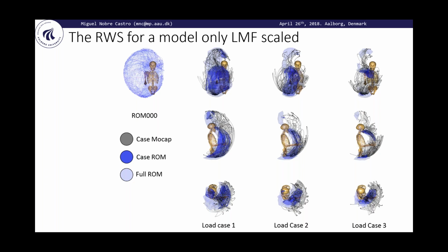So in order to assess that, what we also did, and as you can see here, these light blue clouds that I'm also showing, the light blue shapes. What we did is that we performed the inverse dynamic analysis simulations using all the points that were collected during the no payload case tasks, and we performed an inverse dynamic analysis on each one of those, and then we assess if the model is too strong.